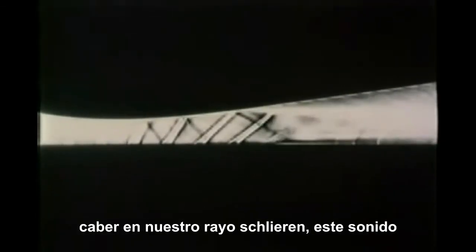In fact, the shock wave in this channel turns out to be not a single normal shock, but a complicated system of non-steady oblique shocks. The boundary layers are separating from the walls of the channel. This is because certain viscous effects are exaggerated when we make our channels small enough to fit into our Schlieren beam. The sound you hear is being picked up by a microphone at the channel entrance. Noise from the valve and piping can only propagate upstream to the entrance if the entire flow is subsonic.